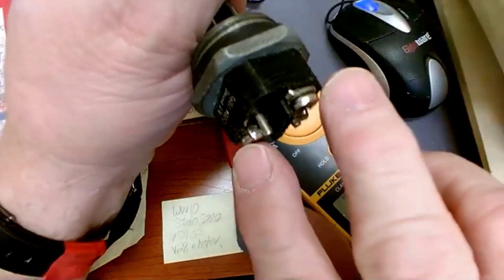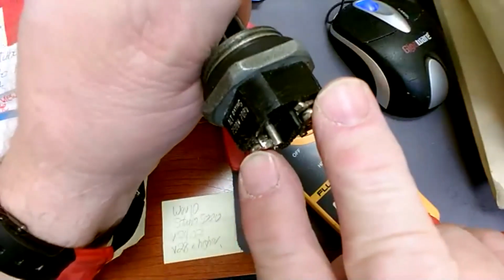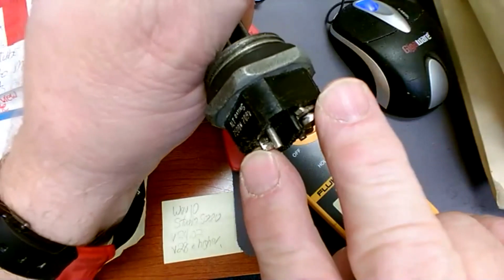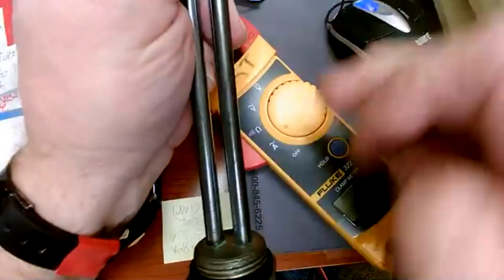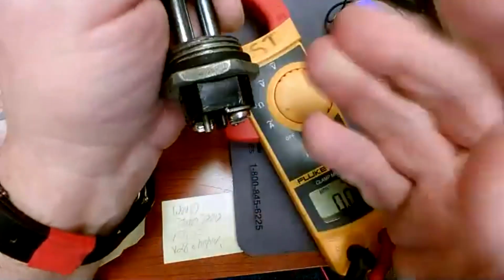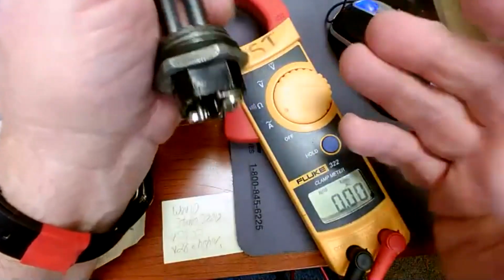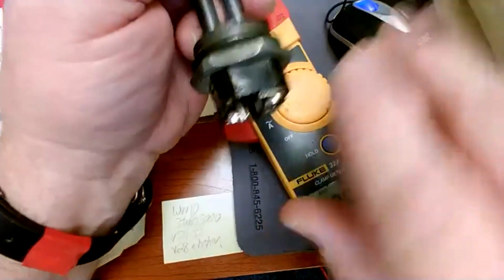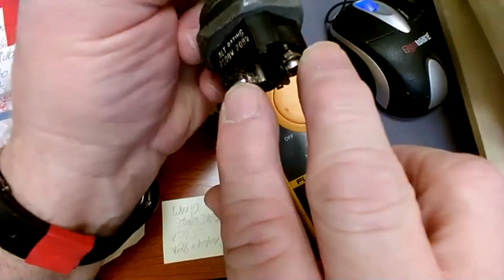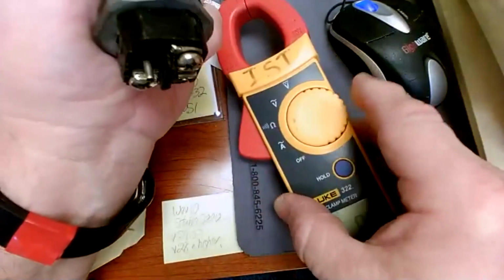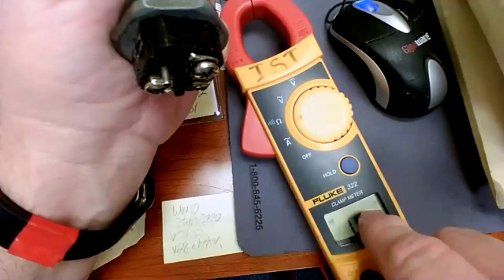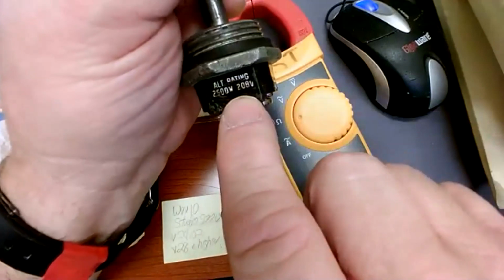So that's your symptom: if the element's burned completely in two, you would read voltage coming from the thermostat into here, but it wouldn't draw any, there would be no current flow through it, because you actually had a broken element on the inside, an open circuit. So then if you want to prove that it is an open circuit, you shut the breaker off, make sure that it's dead here, remove the wires, and then put it on ohms, check the ohms like we just did, and see, does it match your calculation.